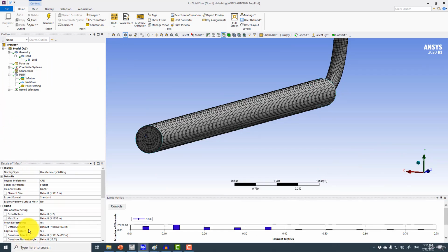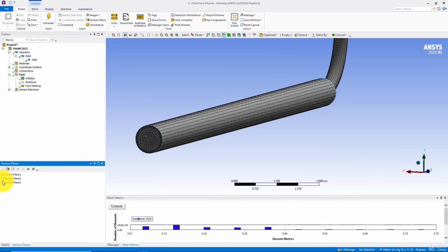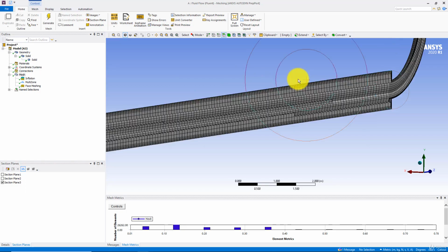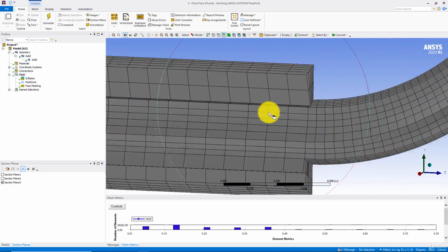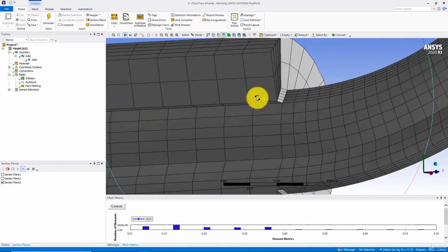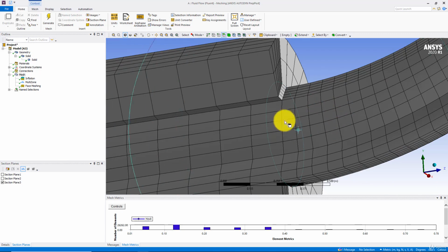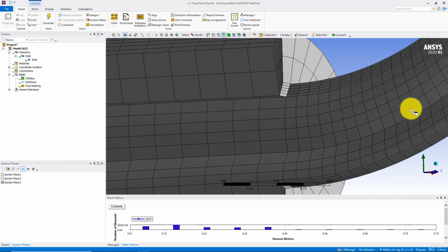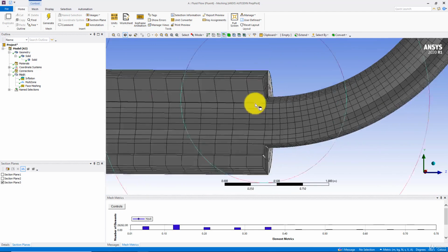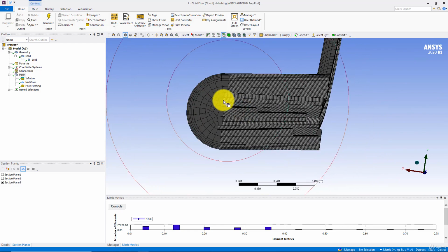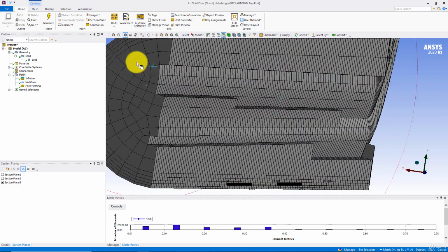And if I take a look at section plane 3 and click on the whole elements, we can see that we have these prism elements, and in between them, in the interior of the geometry, we can see that we have the hexa elements which are going inside the geometry here. So we can also create the multi-zone mesh with all these hexa elements, and also we have control over the boundary as well. So all this can be done inside the Workbench ANSYS meshing with a few clicks.